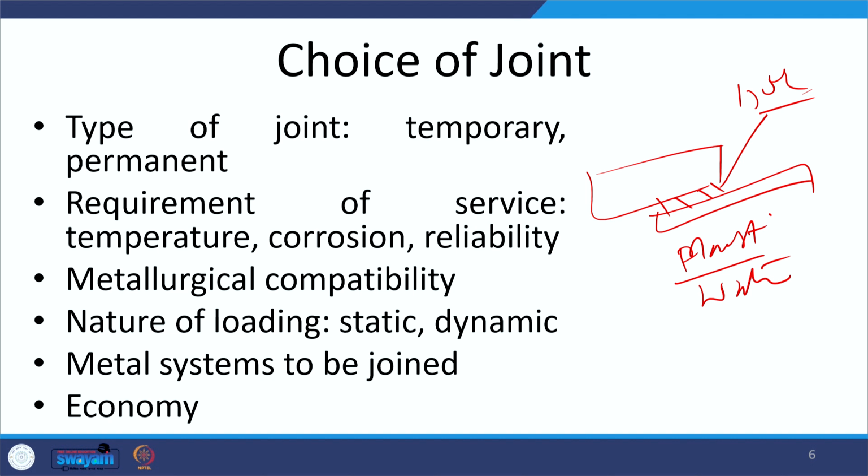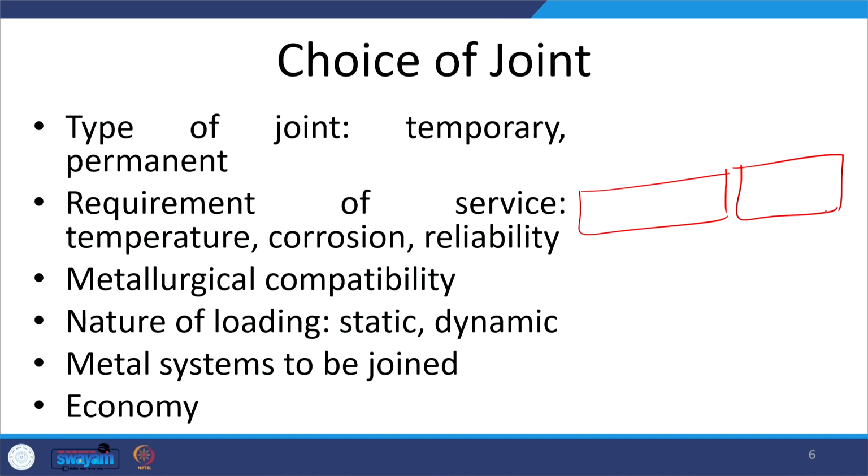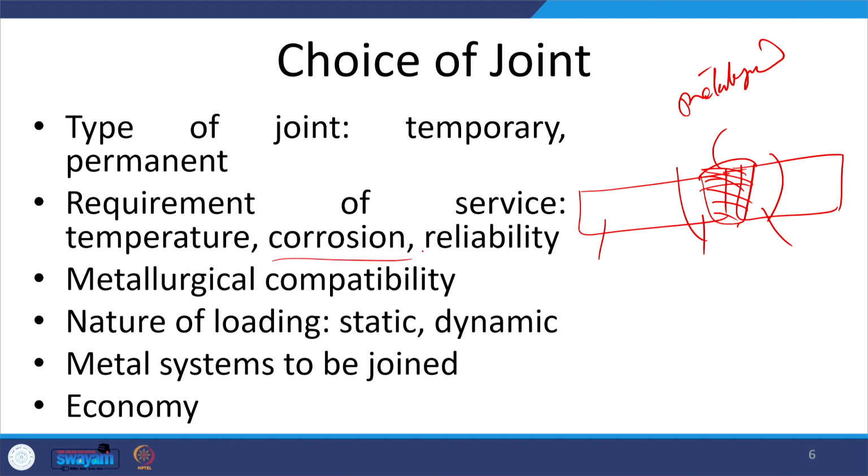Likewise, whenever any kind of joint is made by a welding process, whether solid state joining or fusion welding, we see a lot of undesirable metallurgical changes. These occur not only in the weld zone but also in the heat affected zone. Because of this heterogeneous microstructure, the corrosion resistance of the different zones of the joint becomes different. So, if the joint has to work in contact with certain corrosive media, then it must be able to resist the corrosion. Otherwise, localized selective corrosion will lead to premature failure or poor performance and reduced life of the joint, and that in turn will reduce the reliability.